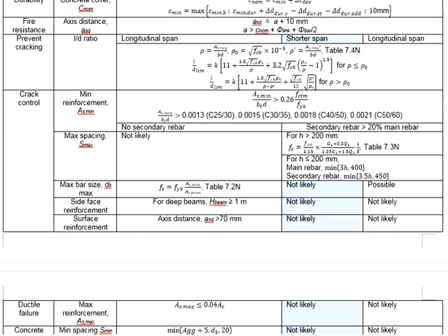The reinforcement bar used is likely to be small, and if you know that you are providing low reinforcement, the chances of exceeding the maximum bar size is relatively low. The common bar size used in a typical slab will be H10, at least based on my personal experience. You can check for the maximum bar size, but it is not likely to be exceeded.